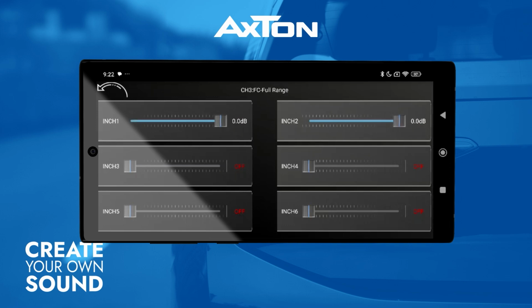If it turns out later that the center speaker distorts due to a high input level, the input levels of both channels can be adjusted accordingly until the desired result is achieved. The other channels are again moved to the left or set to a minimum.